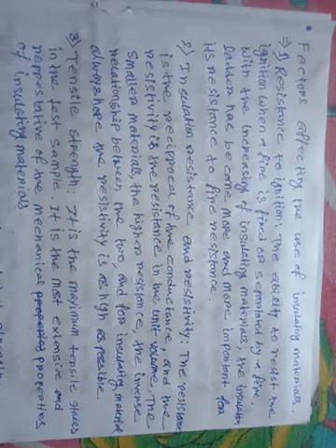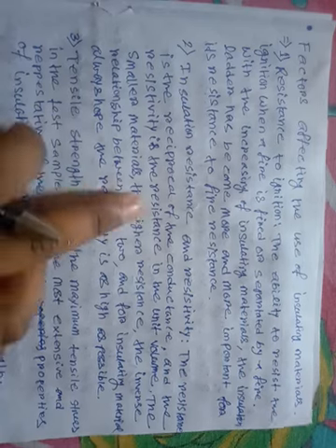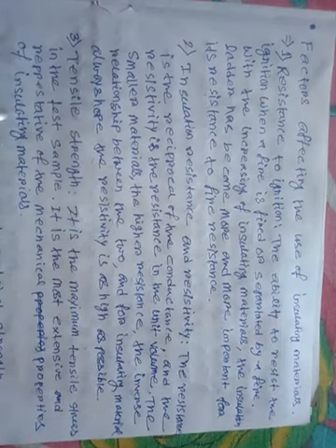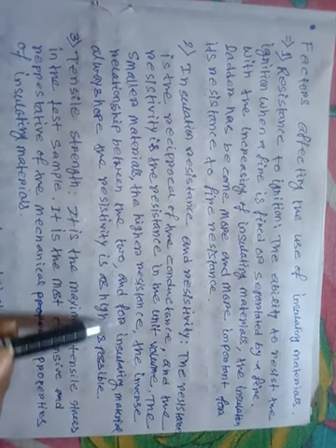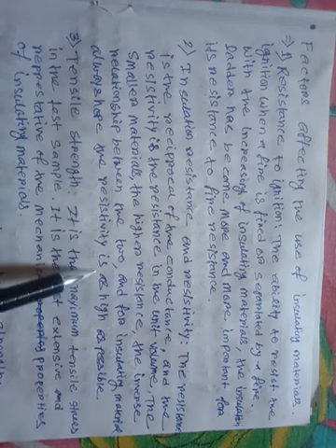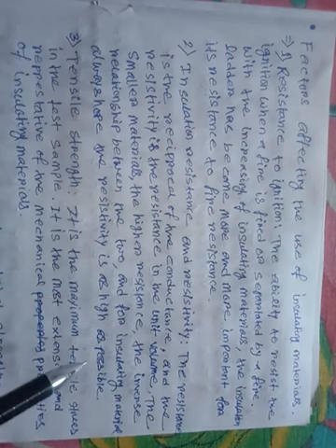The insulation resistance and the resistivity. Resistance is the reciprocal of the conductance, and resistivity is the resistance per unit volume. The smaller the resistivity of a material, the lower its resistance; there is an inverse relationship between the two. For insulating material, we always hope the resistivity is as high as possible.